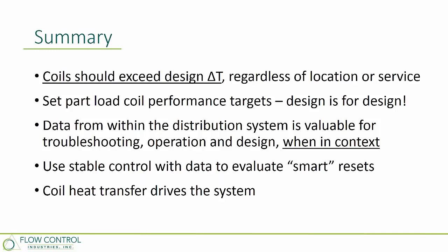We know that there are a few big influencers on the way that coil operates, but the control side of it, that control valve in particular, becomes a really big factor in determining the total outcome, right? We take all of these inputs in there, and we have to deal with that flow to deliver the right discharge air temperature to provide the comfortable environment, right? And if we do that correctly, then we start to see the benefits, we start to see the side effects, the higher delta T's and the lower flow rates in total operation.